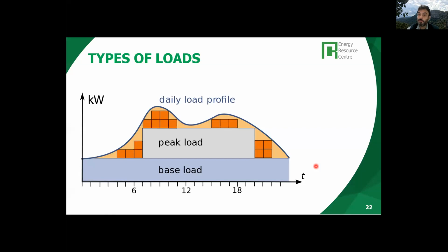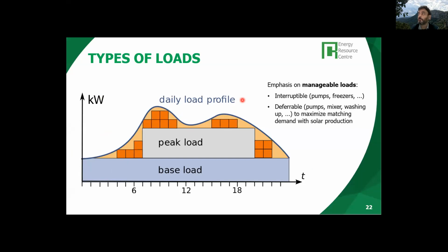And we could also have different patterns. Imagine the consumption in a school or a public building. We could have one or two months in a year when there are holidays and the consumption is reduced. So establishing the daily load profiles is important to understand how to better design the PV system.